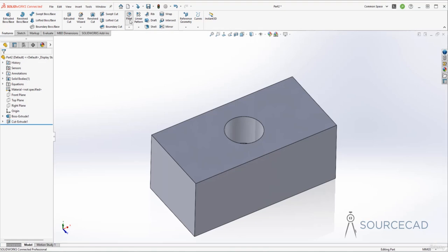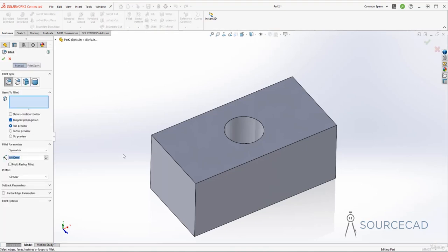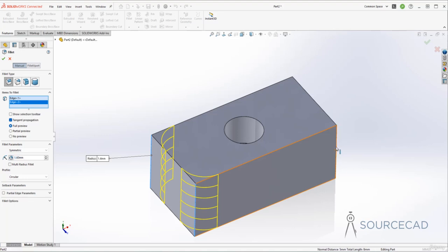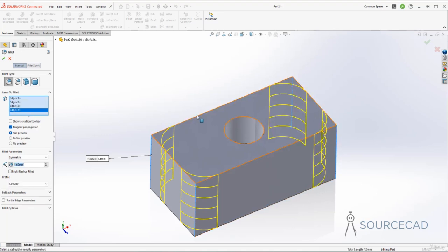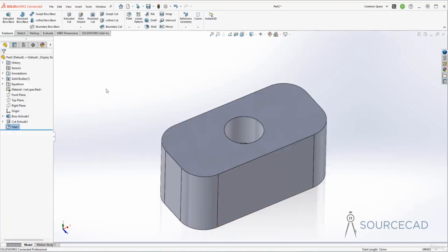Now fillet, and I'll define fillet also using fillet value. So I'll just go to this one, the fillet parameter, the value option here equals global variable, and we have fillet. All right, just click OK, and now select the edges. So I'm going to select all of these edges for the fillet. All right, just click OK, and we are done.